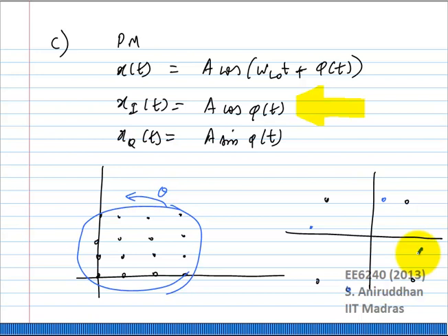So, in other words, what I mean is, you expected to demodulate at a particular frequency, right? You expected the carrier to be at a particular frequency, but it's not. In other words, you thought you were receiving omega LO, you are mixing it with omega LO and taking it to baseband, but you are actually taking it to some, maybe half a hertz or 1 hertz. Actually, that's a lot. Correct. You will get a periodically varying phase. So how do you take care of that?